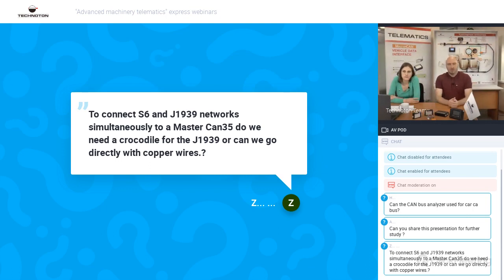Normally, our devices like the display work in active mode, so that doesn't allow us to connect to the CAN bus directly. This means normally we use our contactless readers to work with the standard CAN bus, like the FMS Crocodile, to protect even the CAN bus from active requests of the GPS tracker and system.